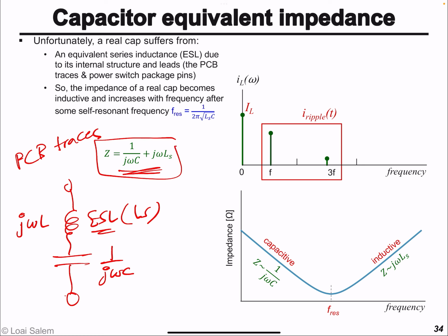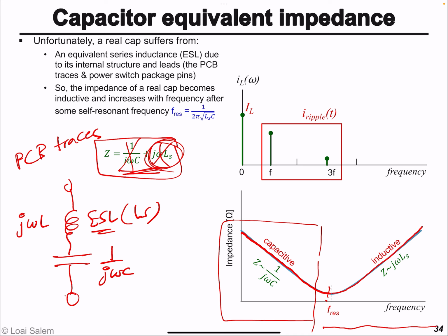Initially, the second term is 0, and essentially we have a capacitor. The inductance does not appear until the self-resonance. We'll find that the capacitor term becomes almost 0, and the second term becomes the dominant one, and the capacitor behaves as an inductive reactance. Obviously we want to use the capacitor in the range where it's actually a capacitor. We don't want to operate above resonance.